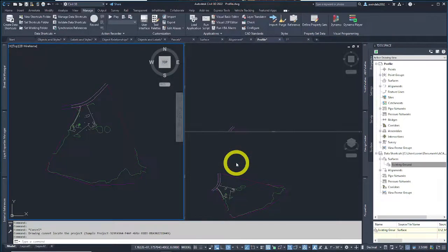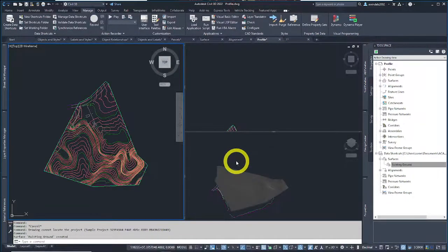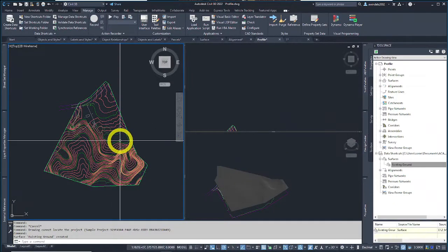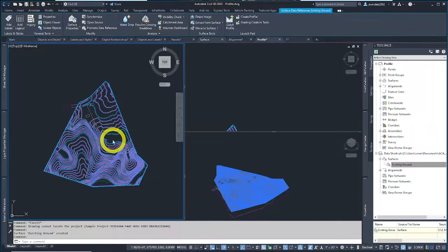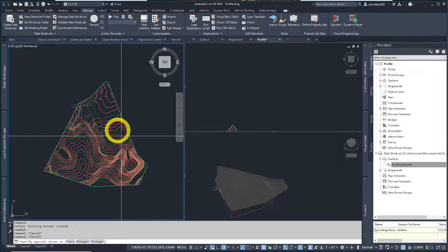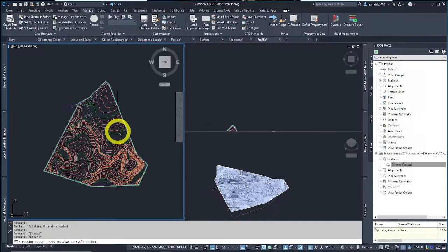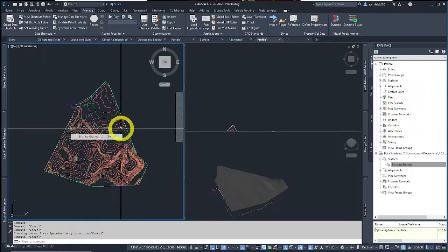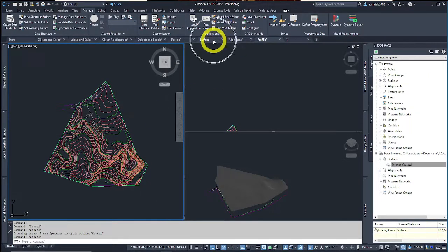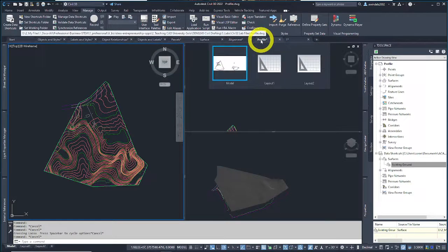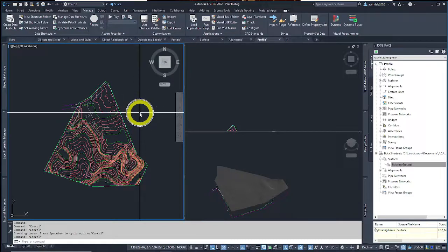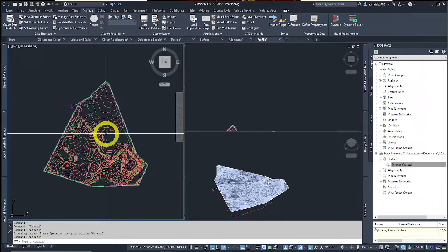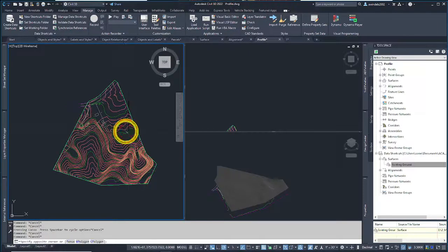We'll hit OK. We're going to do the same thing, steps 12 and 13, but also, see, it's here, it added this surface from this file live into this drawing. It can't be edited but we can change the appearance and the style of it in here. So it's kind of live, pseudo. It's still controlled in the source drawing, the data's in the source drawing, but the presentation is now in the destination drawing. So we can change the presentation of this surface, but not the source data.